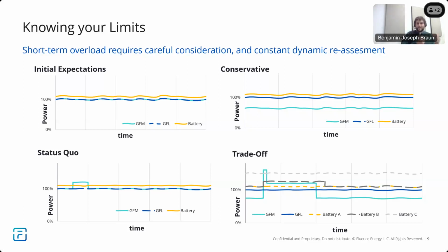We don't need fault current for multiple seconds. Maybe in some isolated grids, they push us to 3 seconds or so, but generally we're talking about hundreds of milliseconds. On inertia, if your grid is near to nominal frequency, and you suffer an event which causes a large rock off, there's only a few seconds before that rock off has driven your frequency so far down or up that all generators start to trip or fall offline.